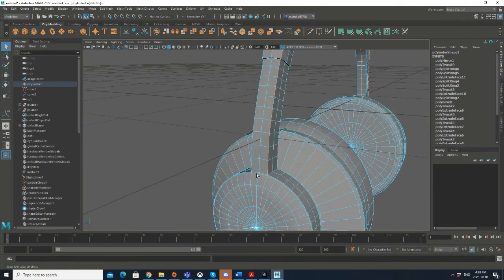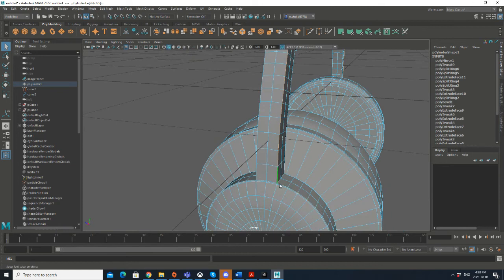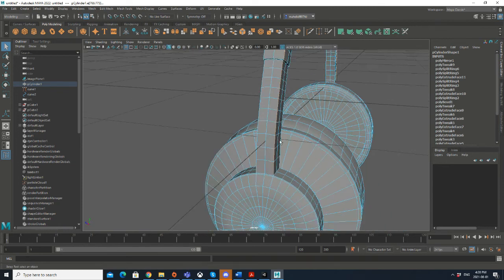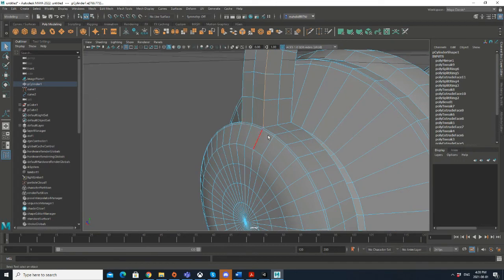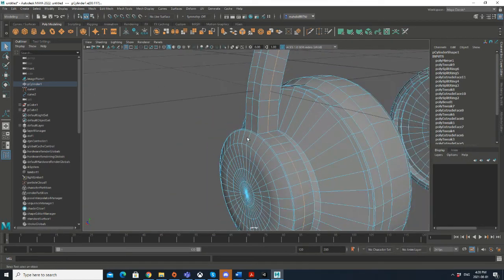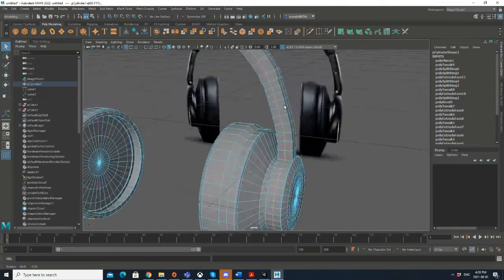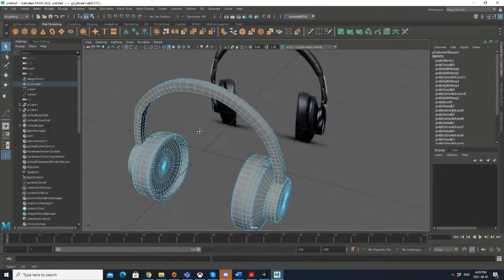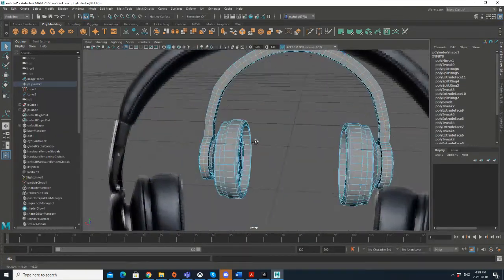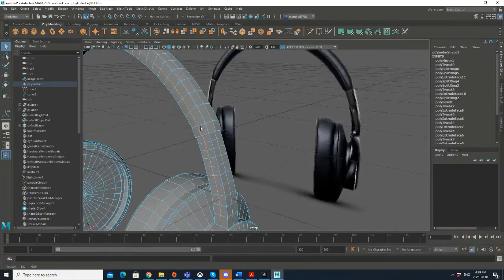For example, for this part, you see that it doesn't know whether to go right, left, or back. That's okay because we have lots of faces connected here. But for these edges which are completely inside the model, I mean, they are not the boundary edges, you can see that it can select all the edges all over your model. So the topology is okay.